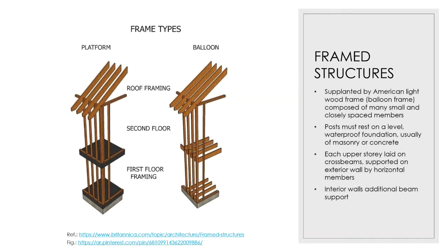They were supplanted by the American light wood frame, also called balloon frames, which you can see on the right side in the figure. They are composed of many small and closely spaced members. The posts must rest on a level, waterproof foundation, which is usually made of masonry or concrete. The upper stories are laid on cross beams, which are supported on exterior walls by horizontal members, and the interior walls are additionally supported by beams.